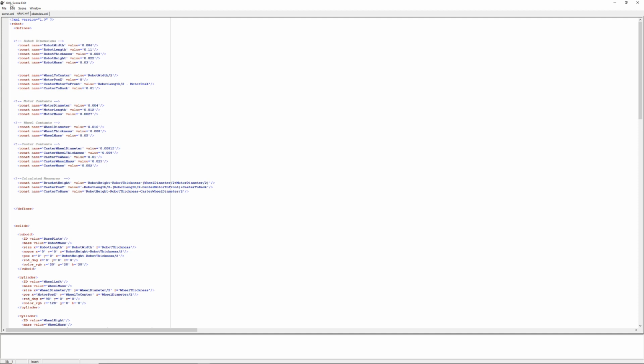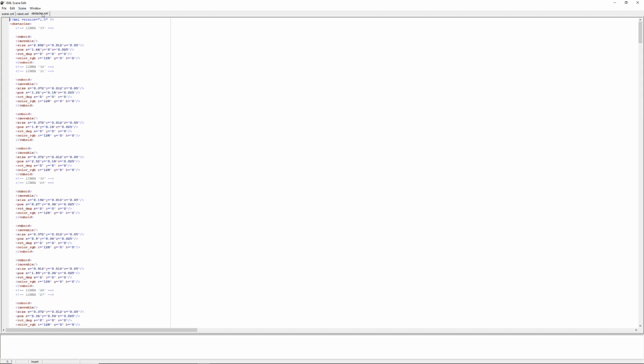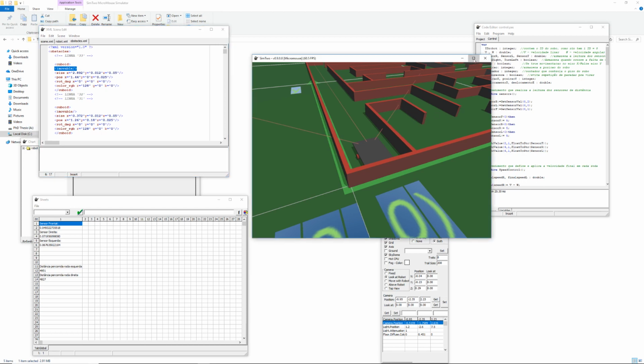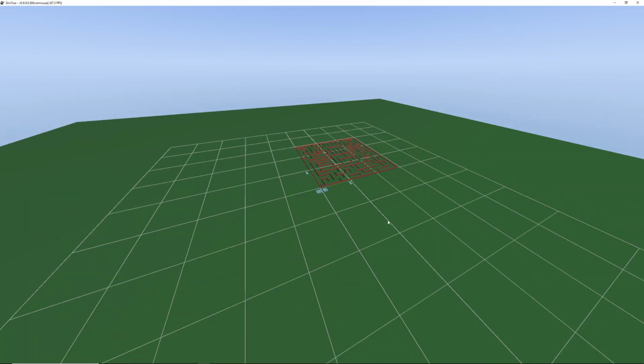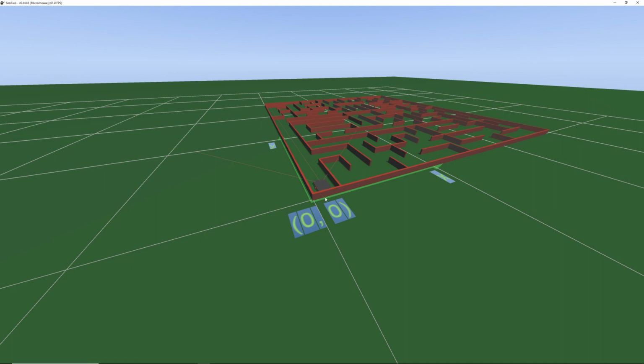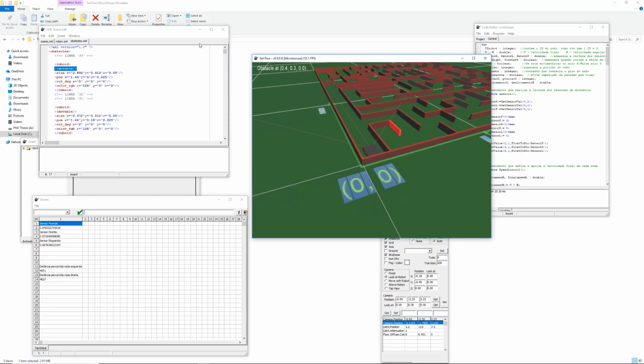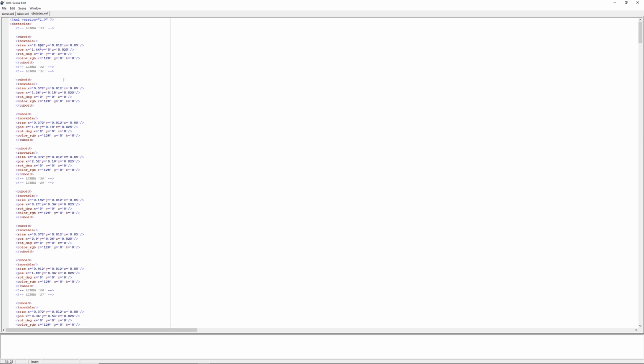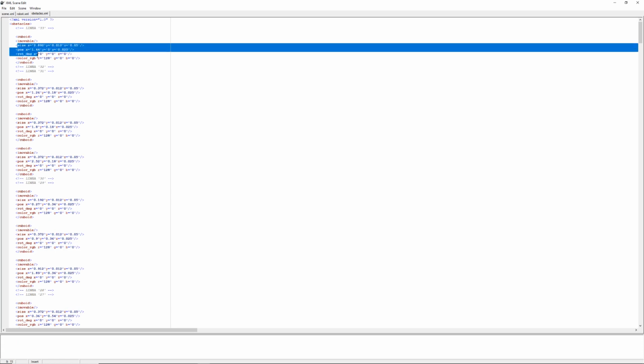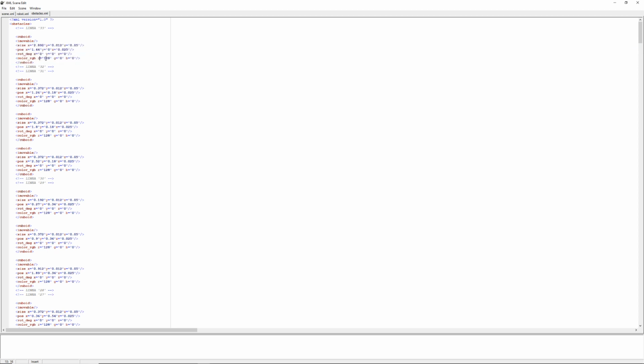The last tab you're gonna see in the XML scene editor is the obstacle XML. So basically the XML, they're cuboids, and those cuboids, they are not movable, they're fixed, because they are the walls of your maze. This is the XML that controls our maze right here. Based on the complexity, we can create more complex or simpler mazes, we can add walls, you can delete walls based on our XML code for the obstacles. And you can see that we have size, position, rotation degree, and a color. You can see they are red.